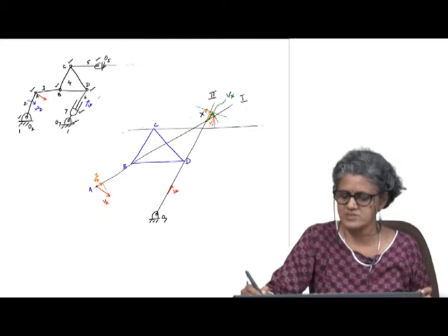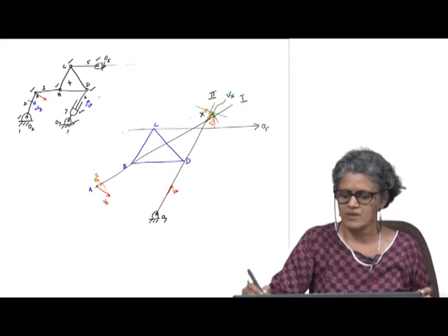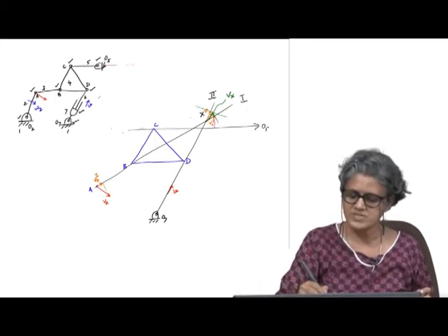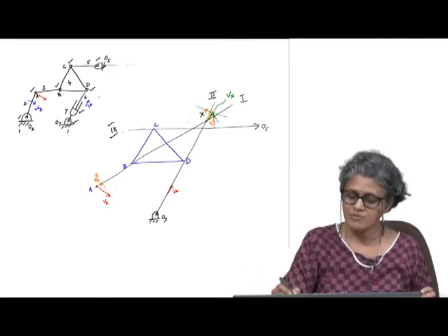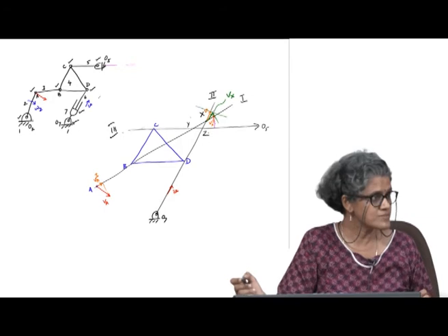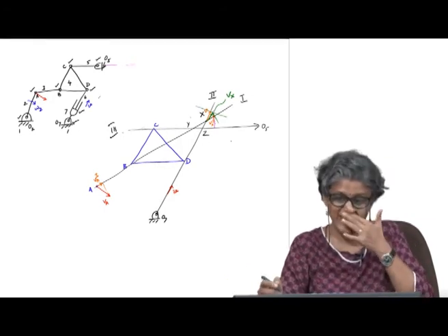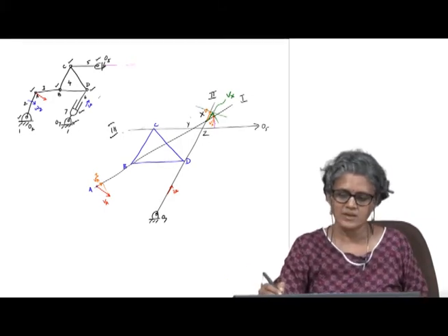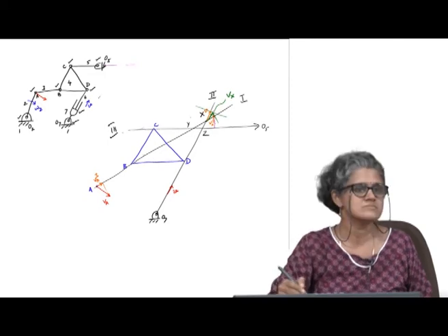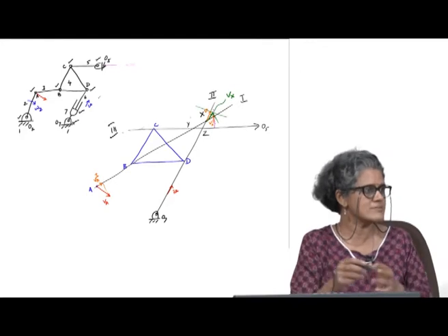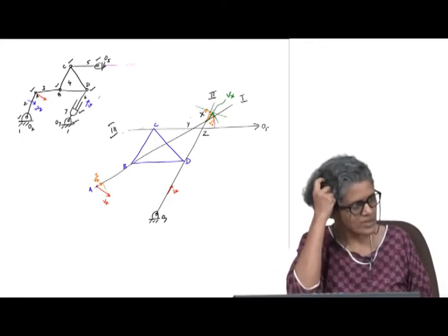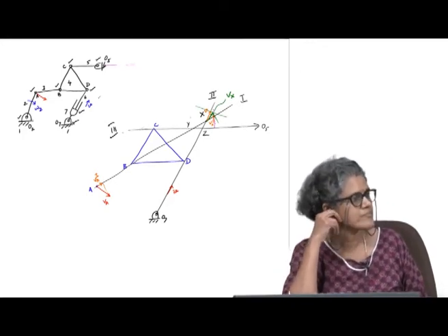Okay, say this is in the direction along C and O5. Then I have Y, I have Z also. I can choose any one of those. Again the same thing, the velocity of X I know along that auxiliary line, I apply that to Y, then do that. Okay. So, we are finding VC without calculating omega.